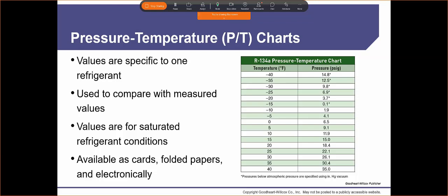around equipment. The reason being, you may get liquid refrigerant that may hit you, and we don't want that getting into our eye. Because if we get, let's just say atmospheric 134A, and that comes shooting out at -15, well, our eye just hit -15 degrees, and that's going to basically destroy our eye. All right, so make sure you wear eye protection.